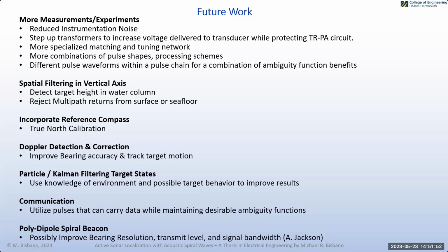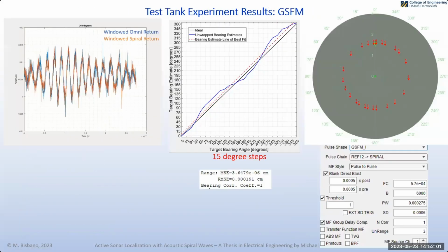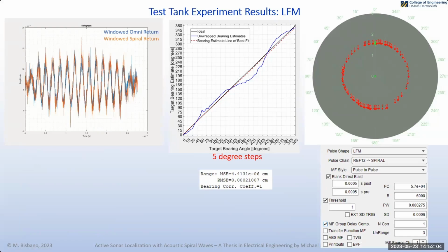Just a few quick points, or at least one that's pretty low hanging fruit. You mentioned on slide 22, 23, maybe 24, this source of bearing error, and you alluded to that it seems to be systematic because when you just tested the transducer, you also saw this. From my experience, this is something that can be corrected easily, and most often it's due to not being in the direct center of rotation as you're rotating it. So it could be the pole is a few millimeters non-concentric to the axis of rotation.